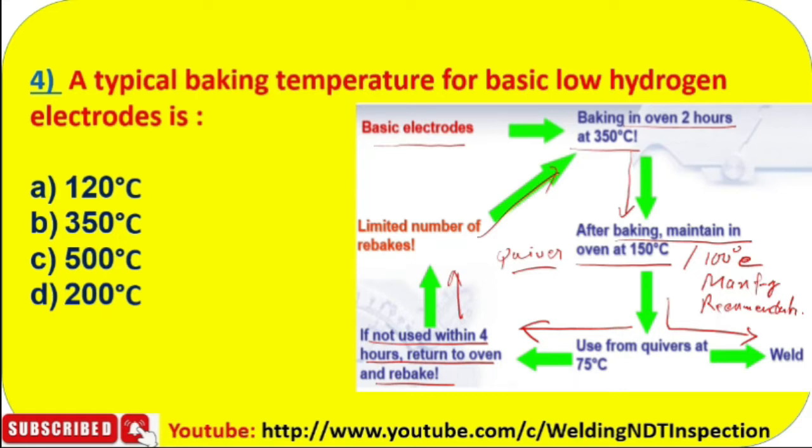First 350 degrees centigrade, 2 hours baking, then after baking it is maintained at 150 degrees centigrade, then it is used for welding. If it is not used within 4 hours, then it returns to baking again. A limited number of rebakes is required. One time is okay.